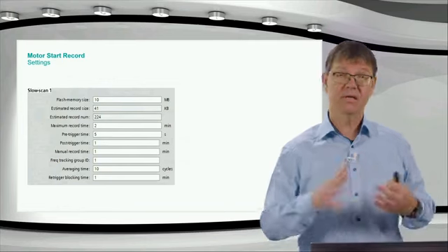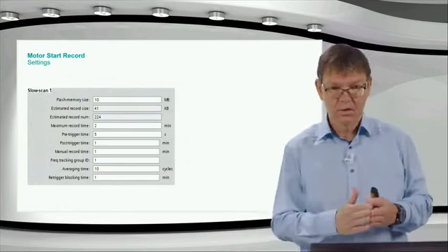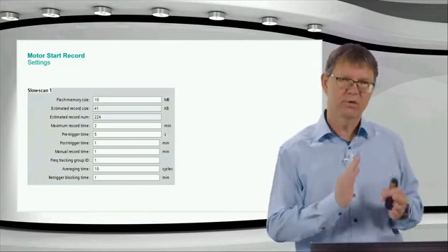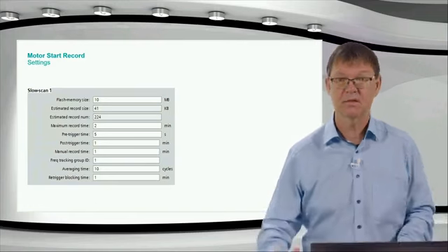And yeah, the fewer values we get in a certain time, of course. If we set this to only one cycle, for example, then we would get a measurement value every 20 milliseconds or 16.6 milliseconds here.